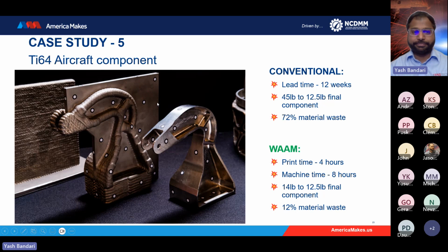All in all, I also want to touch base upon the discoloration. A lot of components that I see, titanium components especially, you would see pretty much rainbow colors. Every color you would see while printing. It could be mostly during oxidation, but it could also be due to heat accumulation. Since we use pre-existing welding standards, we don't put too much heat between the layers. So that is why you're able to see it's just one color and no discoloration that you would see with a lot of titanium components.